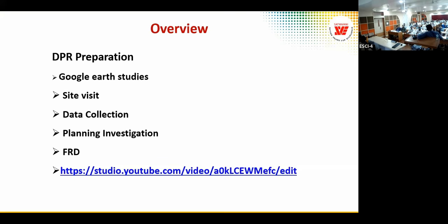I have seen in one project, when we took up the project, there was a geotechnical report. We found it inadequate. We again got it reinvestigated and we got more clarity. Initially they did 5 boreholes in about 5 acres. We did about 20 boreholes in the same 5 acres. But still, rock is something where, unless you do RQD, rock quality designation, that is the test that has to be performed in the geotechnical investigation stage itself.